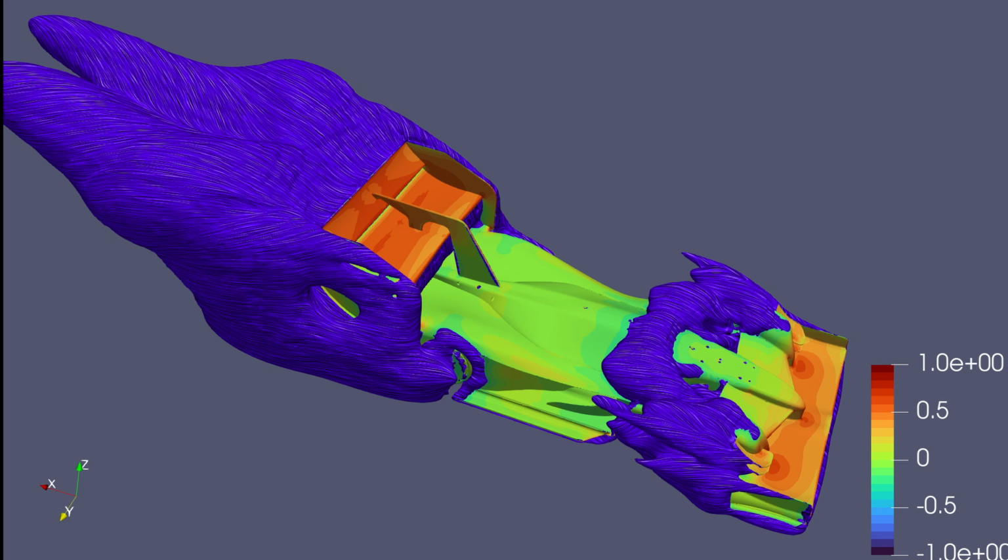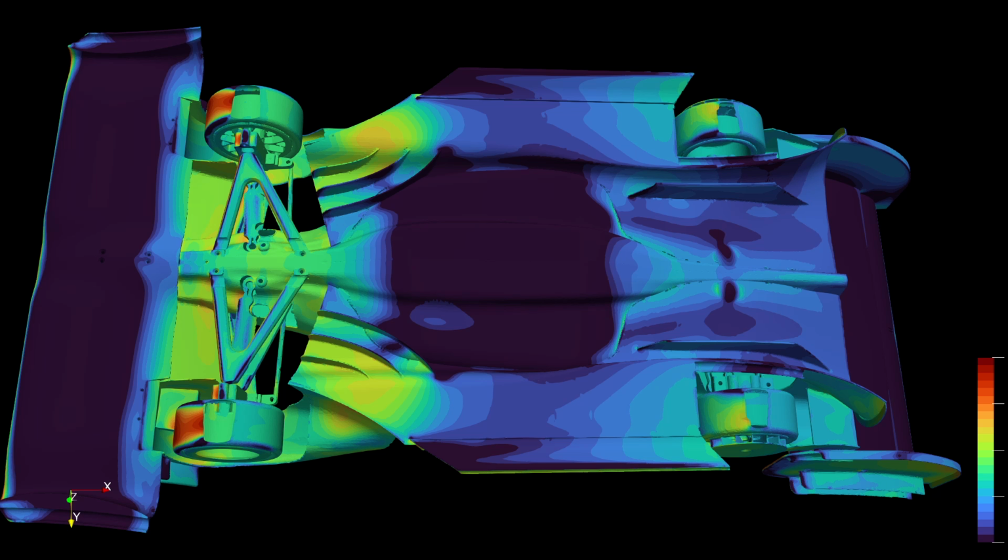I spent a significant amount of time optimizing the shape of the diffuser and these vortex generators, and tried different numbers of vortex generators, different angles, and different methods for creating the vortex. The shape is very important. You want to bring the air in gently and then, at the last second, curve it in a harsh manner so that you get the vortex to form at the end of the vortex generator.